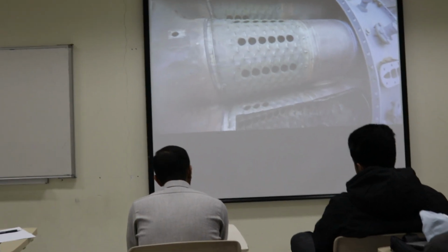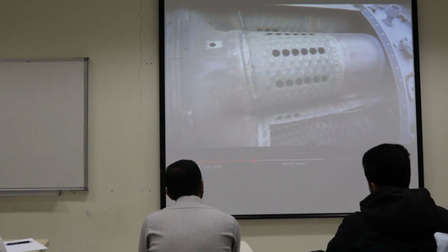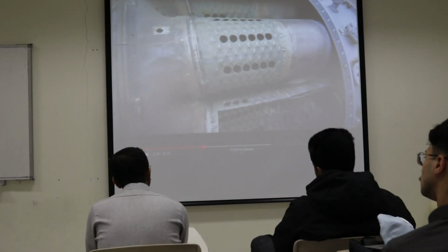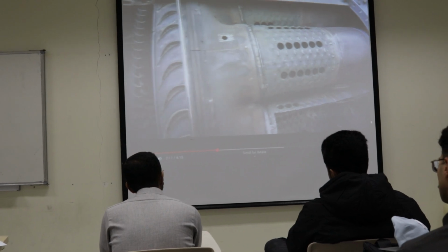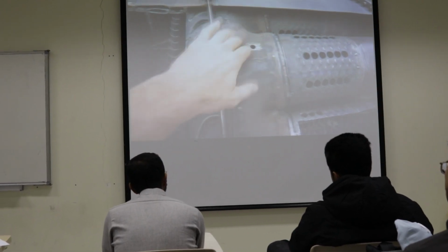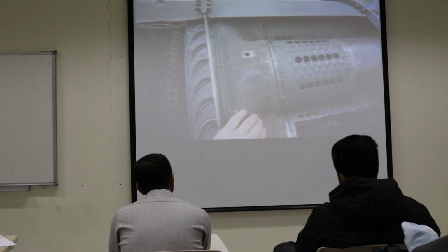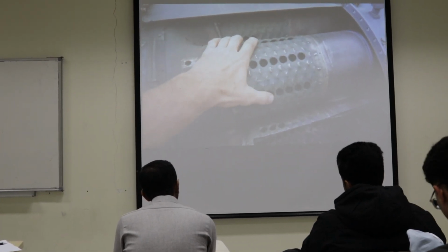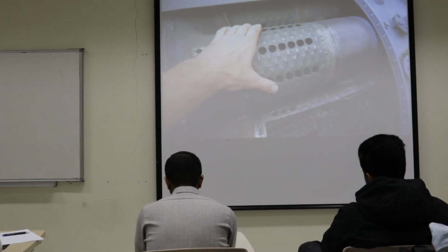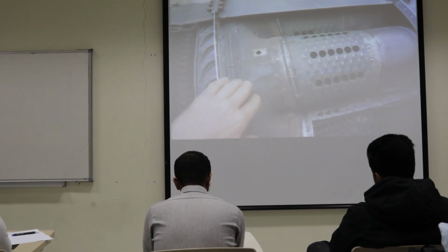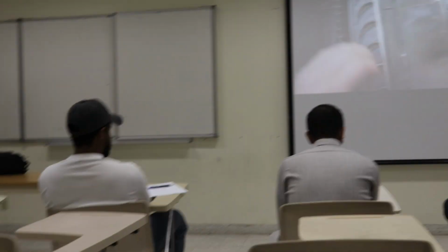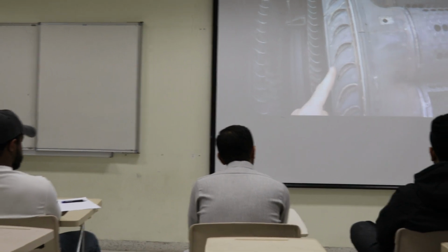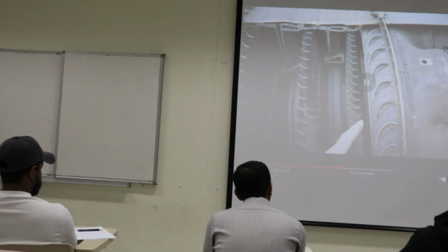See, guys, the liner, and we have the openings for the secondary air coming in to do what, guys? To do the cooling, exactly. Then we can move on. You see here, this is the transition duct, which we've also seen before. It turns the cylindrical outlets of the 10 combustors into an annular ring of hot gases. This is the nozzle. Yeah. This is the gas.